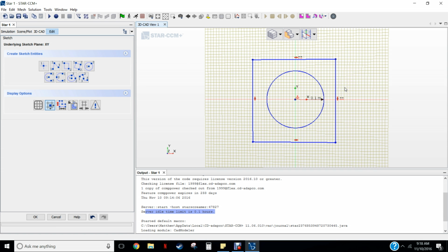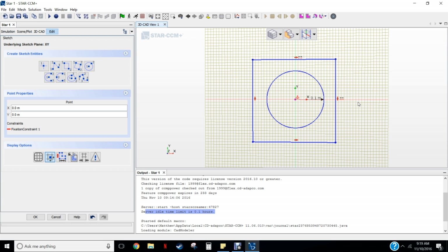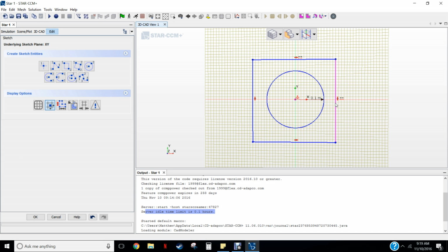We also want to adjust essentially the distance from here to here. We want to change the S value. Unfortunately, since there's not a point right here, we're not going to be able to dimension from here to here, but we can dimension from the origin to here. So in order to set that, we can click on the origin while holding Control, left click on this line, and then still holding Control, right click on the line again,